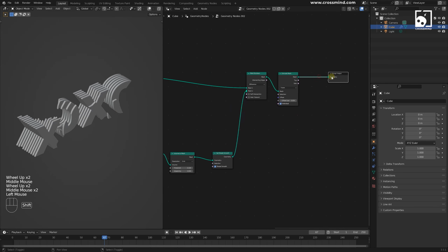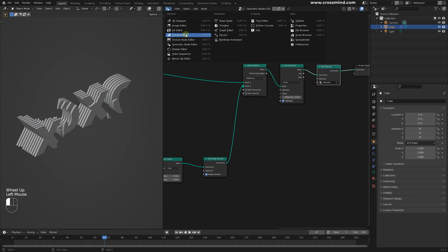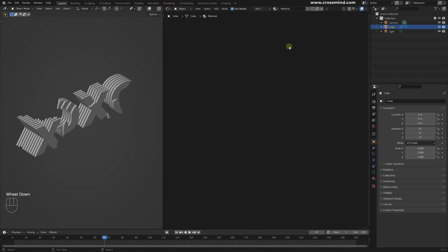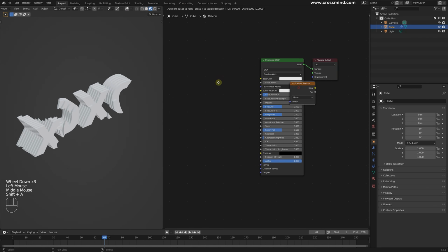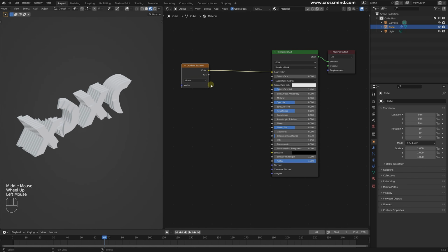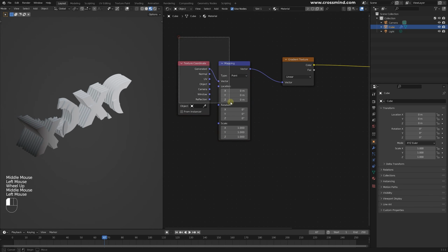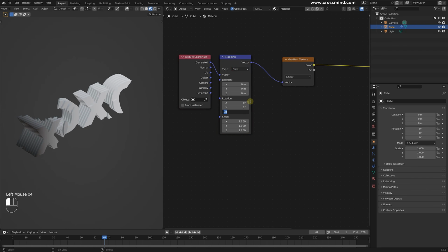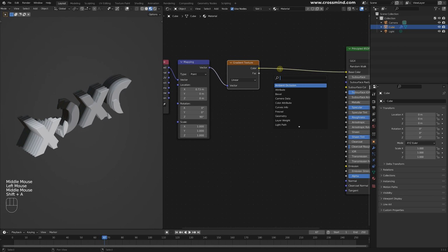Now let's bring some materials to this, set material, and add a material to this. And in this material, we are basically going to bring one simple shader, pretty simple, and this is going to be a gradient. And let's press Ctrl T for the Node Wrangler's mapping coordinates and turn this in the 90° Z and start aligning your gradient to the text.